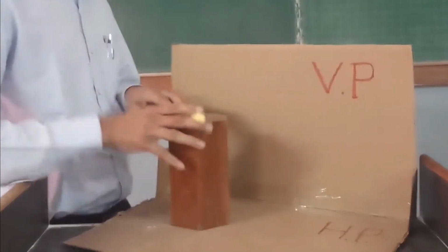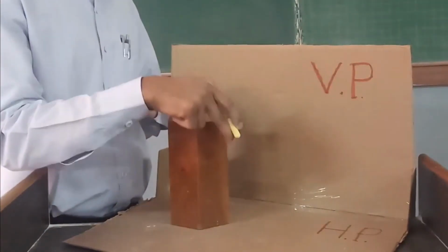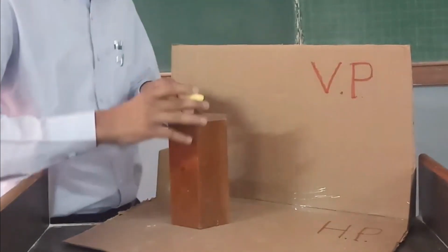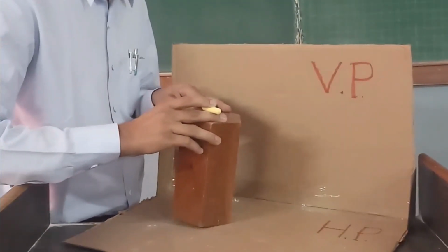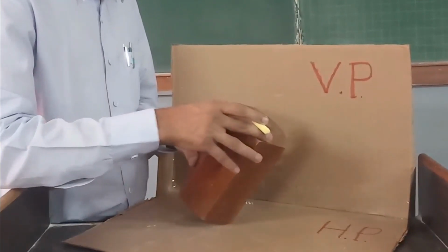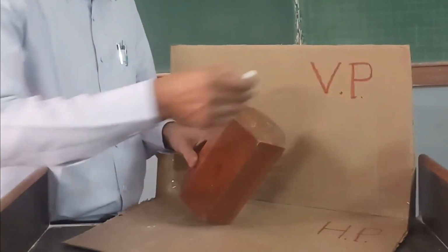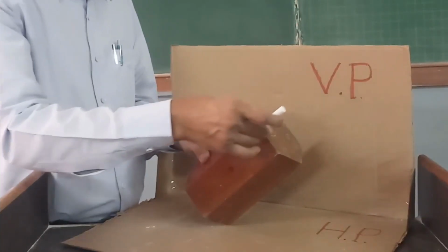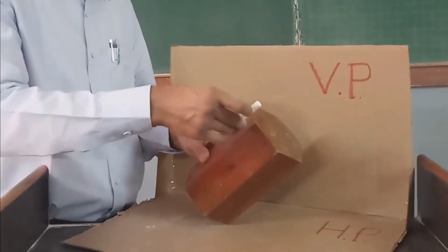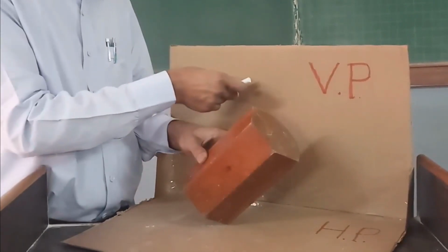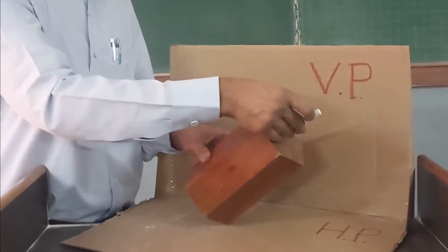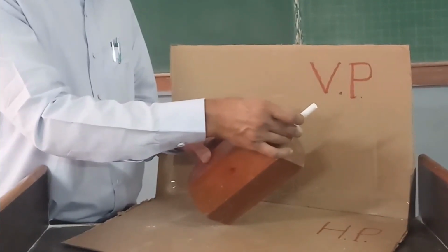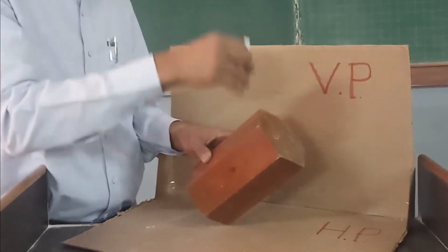Now after this we have to give first inclination. First inclination is to the resting plane, that means to HP, and that is of the axis making 30° with HP. So we have to tilt it about this corner such that we can now see this is the axis. Now the axis is making certain angle with horizontal plane. You can see axis is making certain angle with HP and it is still parallel to VP. So this is the intermediate position, and in this position we need to again draw its front view and top view.